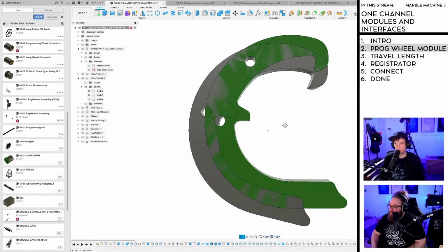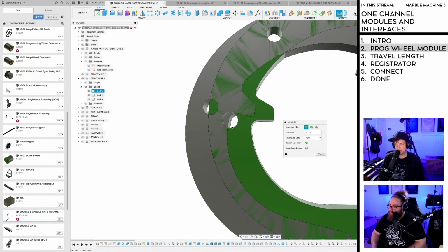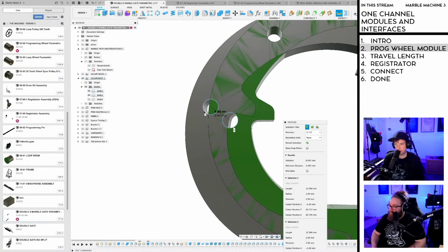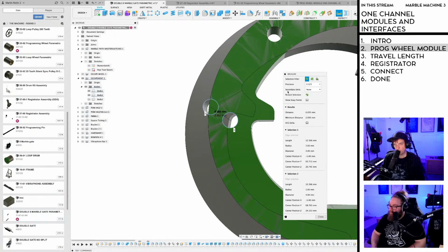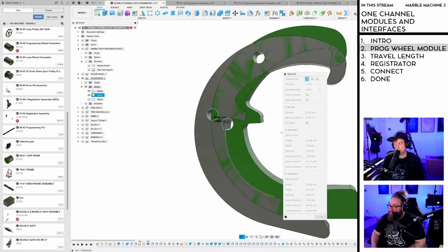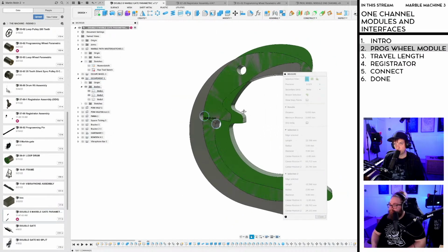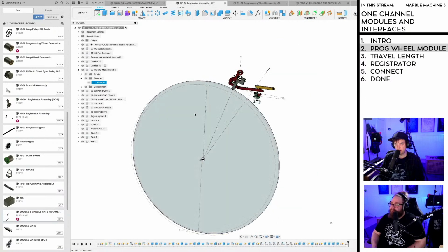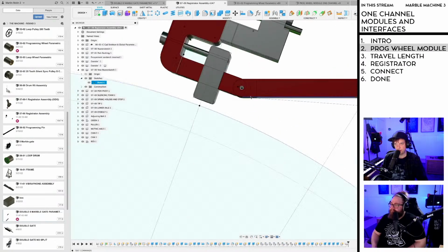This is the 16 degrees of travel that we have. And I think it's about 11 millimeters. So let's measure from here to here. 6 millimeters, my friends. We only need the Bowden cable to travel 6 millimeters to drop a whole marble, which is super, super cool. Which means, and this is the next thing that I'm going to go heavily into.